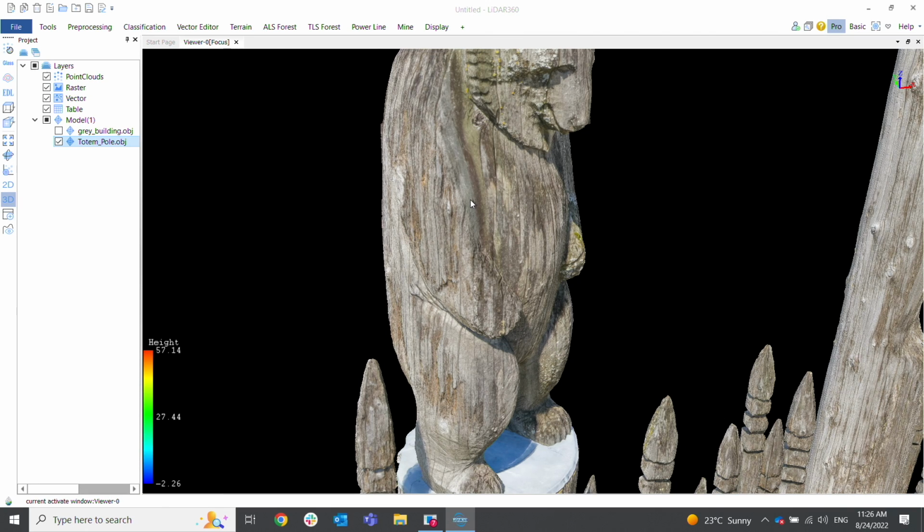But this is great because there's one thing to use this as an artistic type of workflow, but we've seen some of our clients combine this with laser scanning, like a TLS laser scanner, to be able to get a really accurate and precise dimension and shape of the structure. Okay. And then it combines photogrammetry into this to provide that context layer. So some of our clients have been using this workflow for bridge inspections. Scan the bridge and use photogrammetry to provide context, to be able to see some of the rust spots, some of the chips in the paint, and so forth.